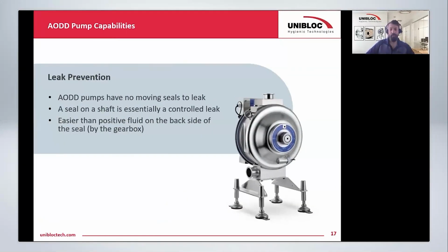And then on top of that, you've got ATEX rated pumps, which is kind of a rating in the UK and the EU for explosive environments. But another kind of hazardous environment would be with chemicals or acids. And so that's another place that the AODD pump shines.